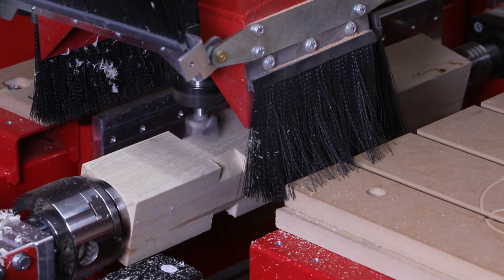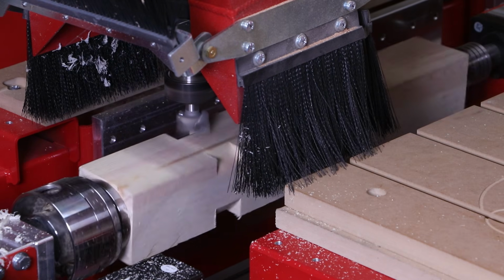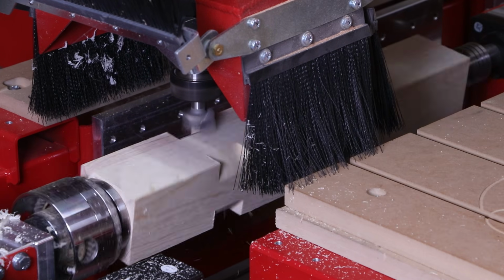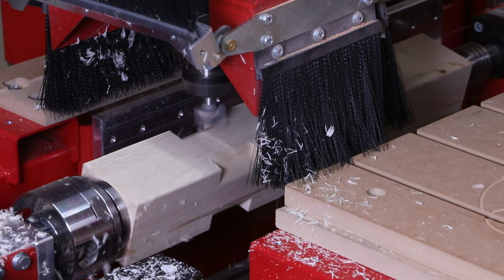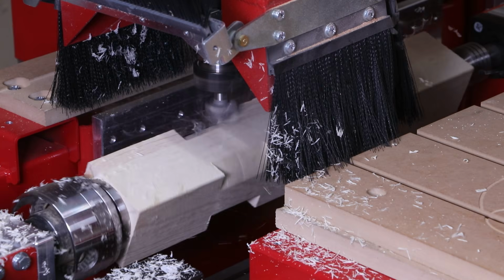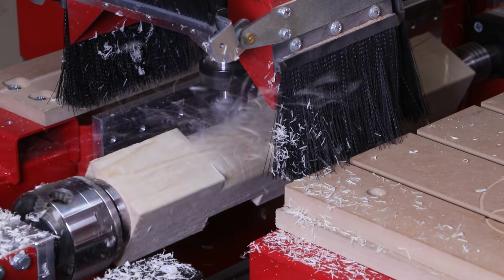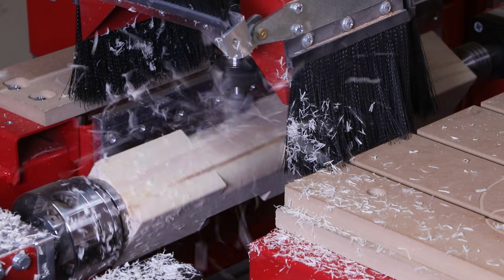After plunging deep enough for the first pass, it does a 360-degree rotation to square off those edges, and then it shifts about 40% of the diameter of the cutter and machines down the length of the turning center while rotating. The reason it shifts off-center is so that the cut is swinging with the grain of the material instead of cross-grain cuts. This gives us a better finish.